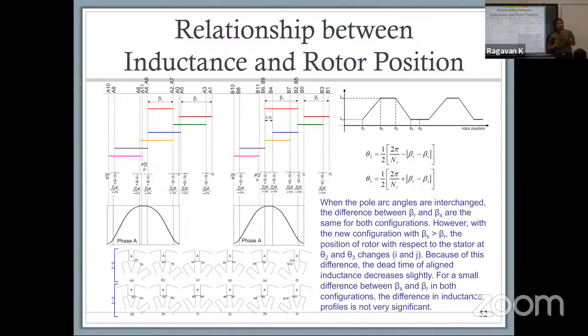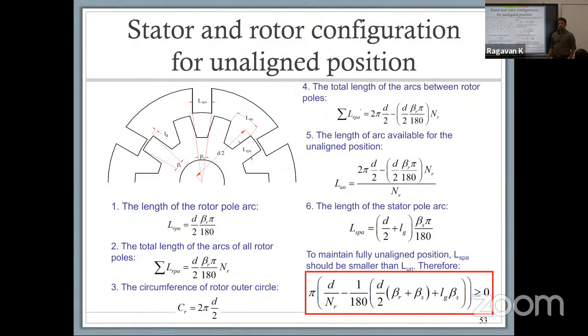So if you have an exterior rotor design, where the rotor is on the outside and the stator is on the inside, because of the diameter, now you have a little more space. So you have some benefits of the exterior rotor type configuration. If you're on the inside, you will need narrower poles that can still give you the expected performance, but you might have limitations in terms of your flux density.